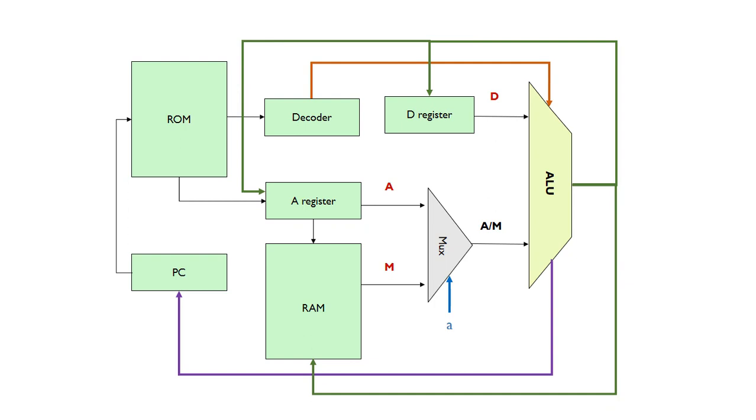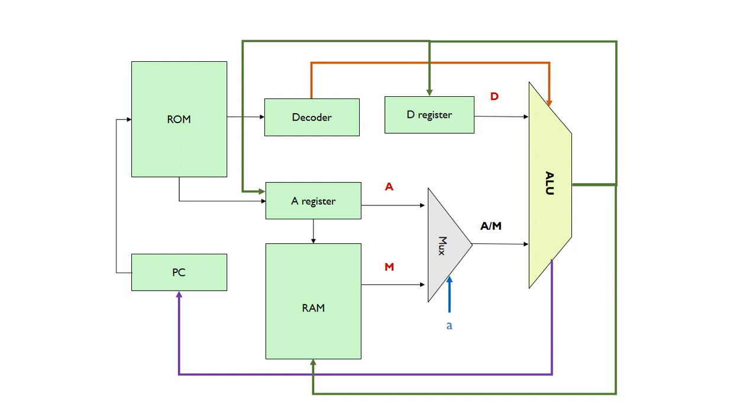And finally, we've got the jump condition. These actually come from the zero and negative flags of the ALU. By checking those flags with 0 or 1, we can determine whether the number is greater than 0, less than 0, or equal to 0, and that essentially decides what happens next to the program counter.